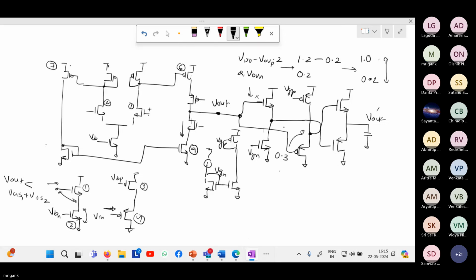So if this voltage has been shifted up, this is completely low and the PMOS is turned on. This is acting like a current source. But what is the role of NMOS here? This shifted up voltage, it will try to bring it down, because again this provided a VSG drop, and then this NMOS is trying to bring it down further towards the source.